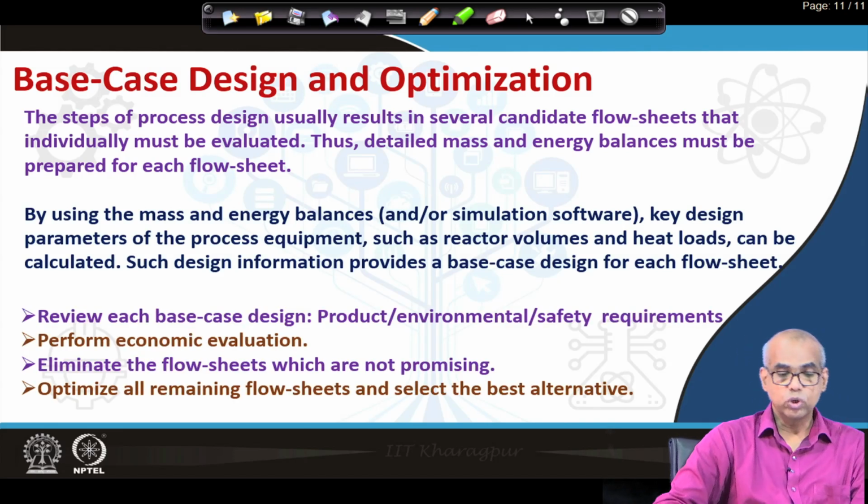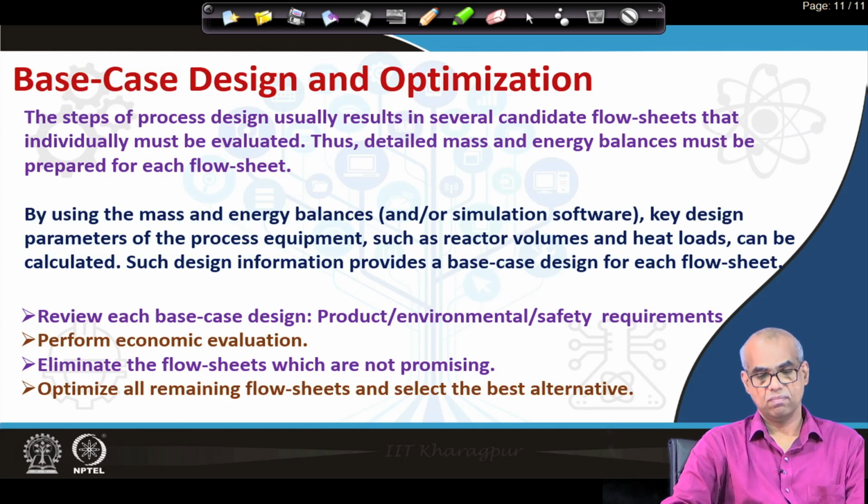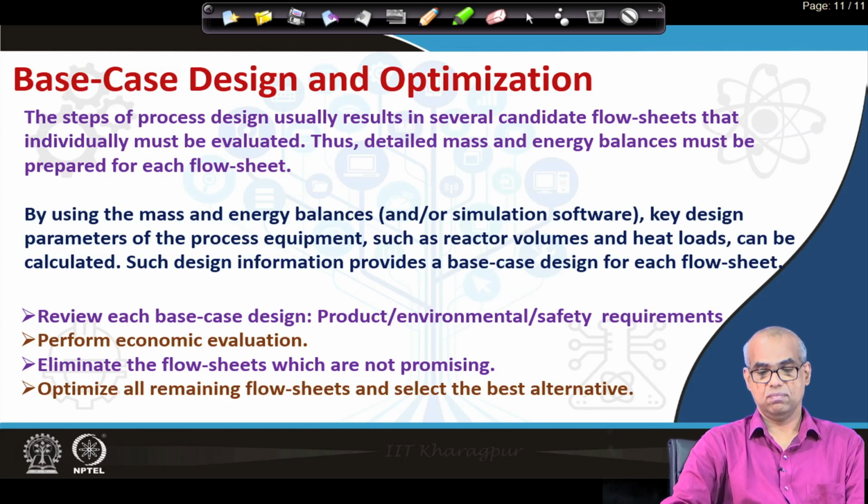Now, we should review each base case design. You must ensure whether these designs meet product specification, environmental requirement, safety requirement, health standards, etc. We must perform economic evaluations on these base case designs. On the basis of these, we should be able to eliminate those flow sheets that are not promising.